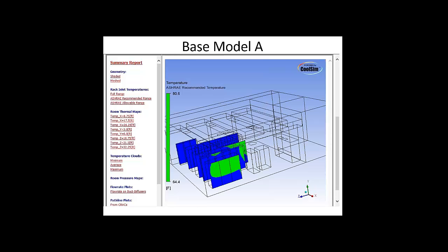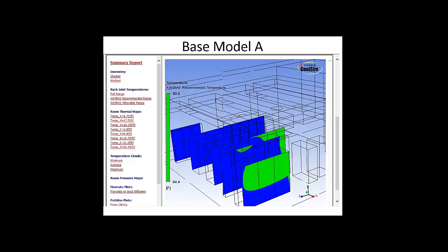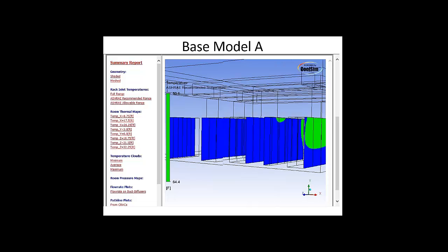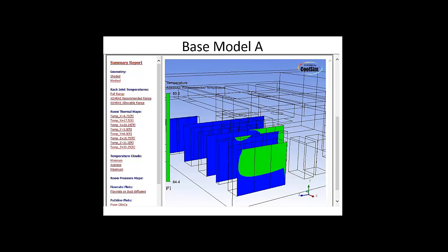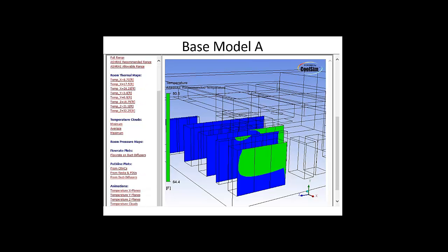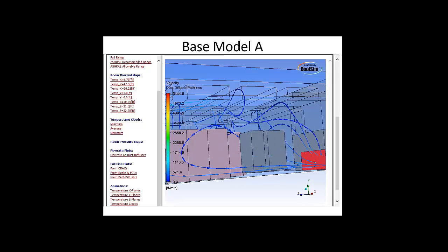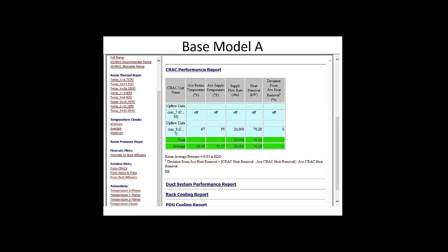There's also a number of plots, but they're fairly straightforward. This one is a conformance plot. Here I'm looking at temperature as it conforms to the ASHRAE spec. There's the spec right there, 64.4 to 80. And you see it's actually failing. It's too cold. These are just the inlets. Some of the rack inlets are supplying air too cold. Other regions are okay. And that's because there's a tremendous amount of air swirling around in this room, coming from the cooling units and down and just swirling everywhere.